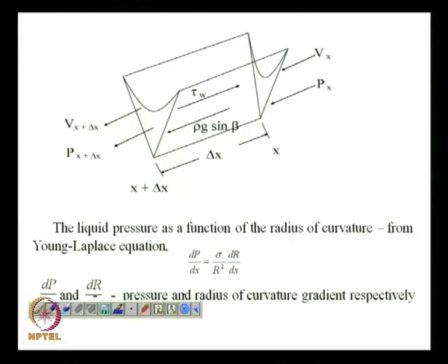Okay. This is a very simple model of fluid flow in a V shaped microchannel, and all of you have done transport phenomena, so just a simple shell momentum balance type of approach can be used to model the flow of liquid through a microchannel between 2 points where there is substantial difference in curvature.